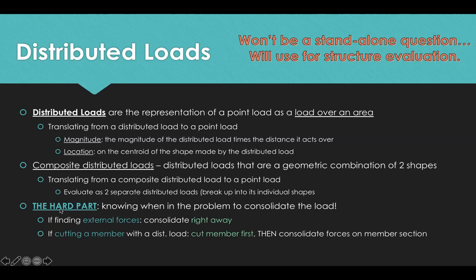And I guess the hardest part with the distributed loads is figuring out when you're supposed to consolidate the load. So really, you're going to do it twice in some cases. If you're finding the external forces on a frame or the reaction forces somewhere, you have to consolidate it into the point load right away, which means when you're solving for something where you haven't cut the member, you consolidate it right away.